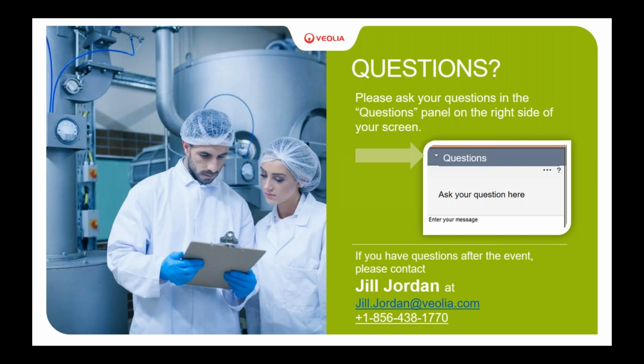In cases like this, we either work with our clients or we recommend that our clients, first of all, look at their flow distribution. So let's say you have a single lift station, hopefully, in your facility where all of the wastewater comes in before it's either sent to treatment or sent to the city. It's very important to see the flow distribution in that lift station. And then at the times when the flow occurs, it would be prudent to collect the samples, or design the sampling schematic. So you collect the samples at the time that the flow occurs, and you test them for the main parameters.